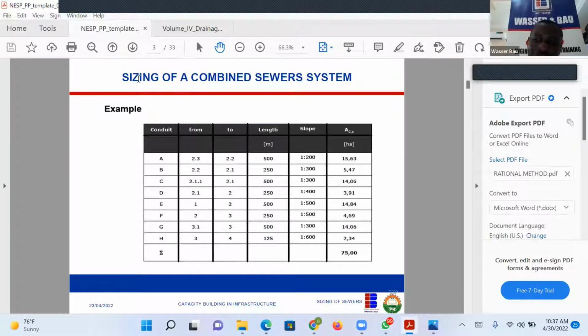When I say runoff, I'm talking about the water that you want to take care of, the flow, the one that is coming from the impervious area, because that impervious side is not allowing water to percolate. It's not allowing deep infiltration, so it is flowing on the surface. So that is the most critical area. That's why I keep saying it.